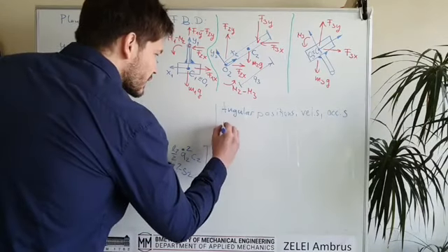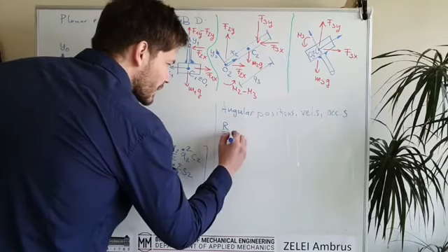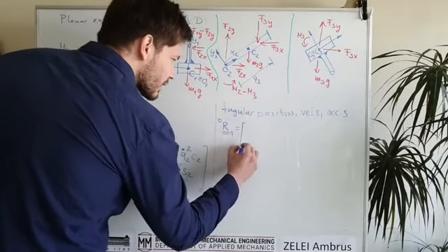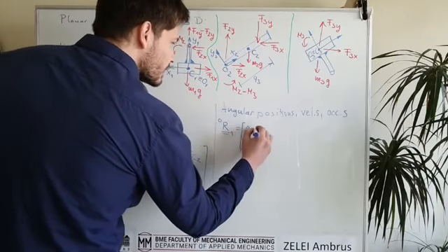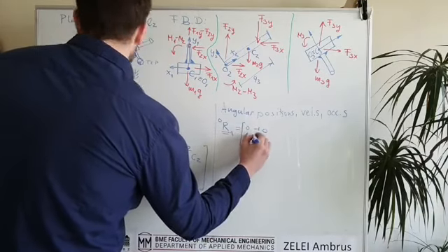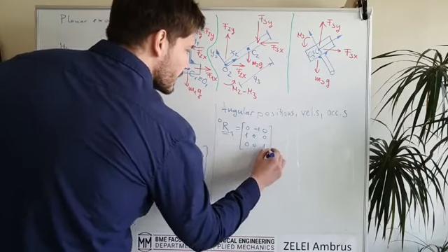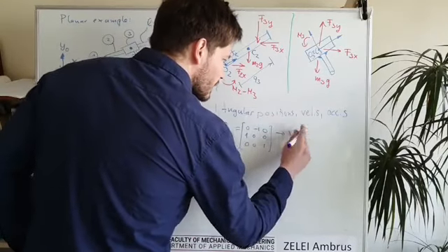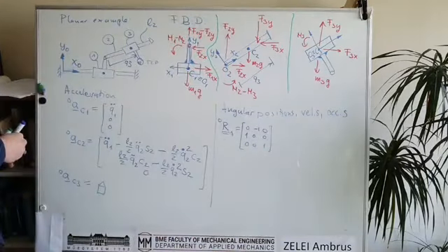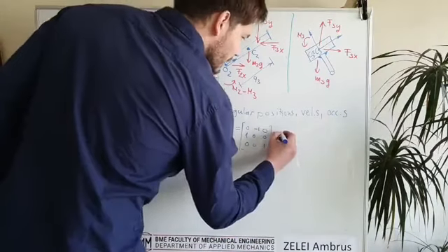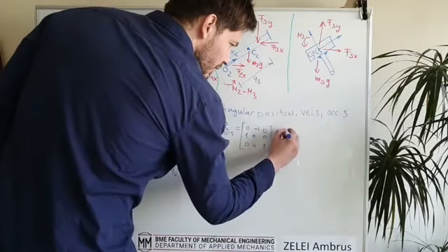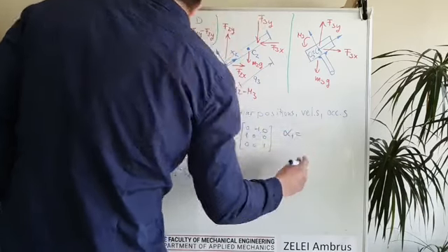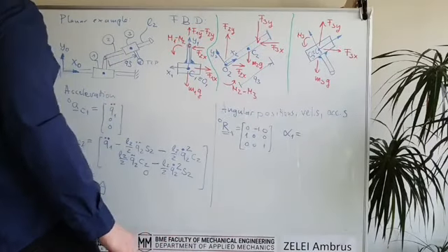So in case of the first, you can take the rotational matrices basically. You can take it out from the homogeneous transformation matrix. The first rotation matrix was 0, minus 1, 0, 1, 0, 0 and 0, 0, 1. And from this you can reverse engineer the angle, so the theta, sorry, we will introduce some new angle. So this is the absolute angle of rigid body number 1, which was pi over 2.